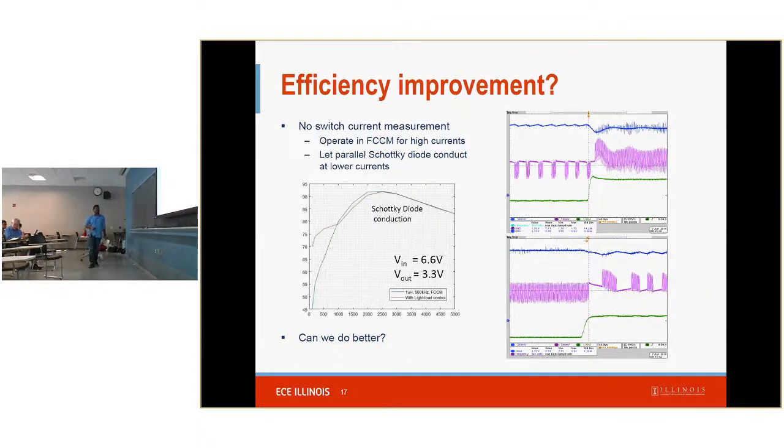So with this, we implemented this on hardware, and we found this demonstration of a negative light load region to a positive CCM operation condition. We can see that there's increased ripple in this region and CCM operation is in this region, and similarly we have the opposite, a negative CCM to positive DCM transition, and it works fine, and we get some efficiency improvement in the light load region with this kind of control.